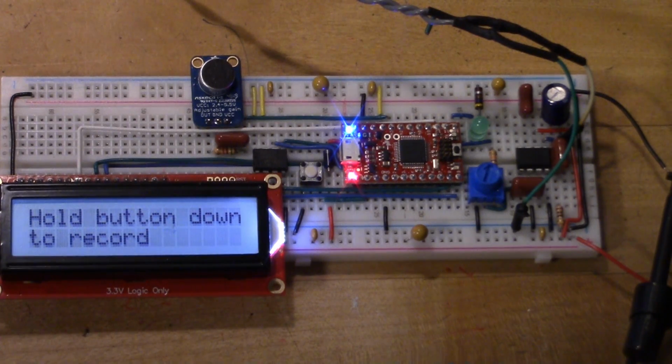All the hard work is actually done in a timer interrupt. There's an internal timer set up to interrupt every 100 microseconds, or 10 kilohertz. Every time an interrupt occurs, the interrupt service routine either does nothing if we're sitting there idle, as we are now; reads the internal analog to digital converter if we're recording and stores the value into the SPI RAM; or, if we're in playback, reads a value out of the SPI RAM and plays it through the digital to analog converter to the speaker.